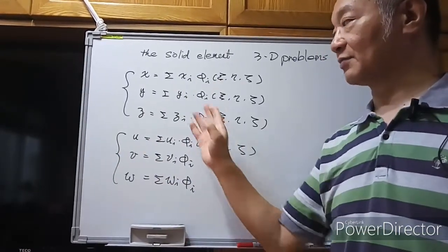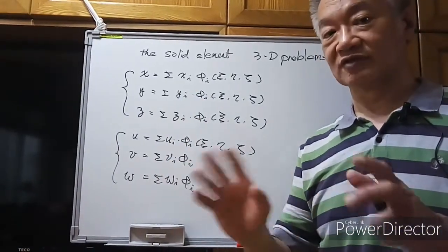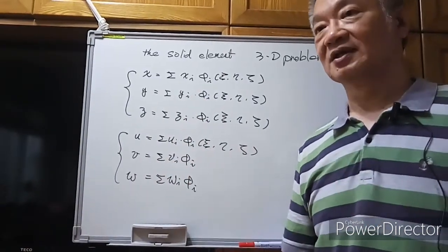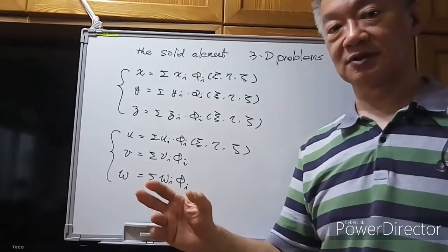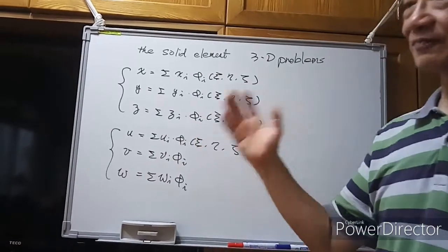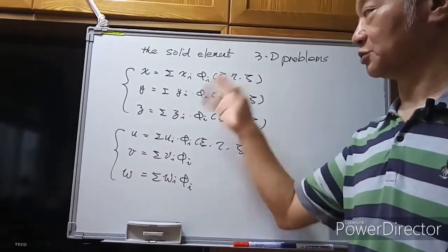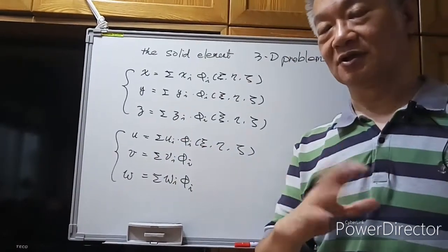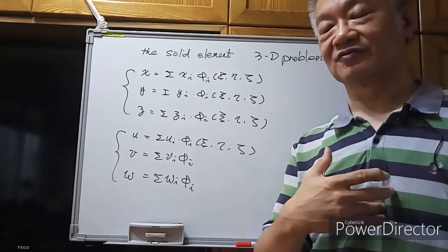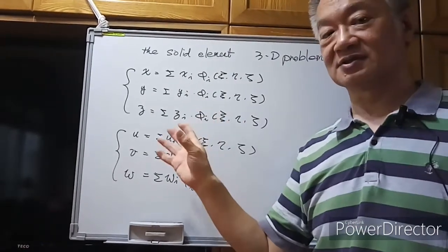If the number of nodal points for these two sets of equations is the same, they are called an isoparametric element. Okay, but I didn't mention that we could use different numbers, since, for my understanding, almost no one uses different sets right now.